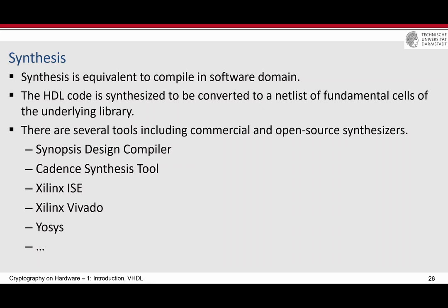It means that the netlist that they generate is not necessarily the smallest netlist, because in hardware, the number of gates that you have or the latency of the circuit that you have are important. And then all these Synopsys and Cadence and the other companies try to build the algorithms to make more efficient hardware. Otherwise, it's not hard to build a super large function that actually works and performs the operation that you want, but is super, super large. You know? This is not hard to do. And Yosys, I wouldn't say that Yosys is bad, but Yosys is not meant for optimization in latency and area. But of course, you can check whether it's synthesizable, and also the result of Yosys you can simulate.